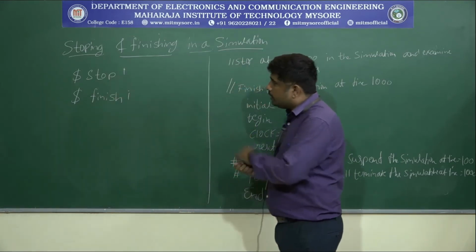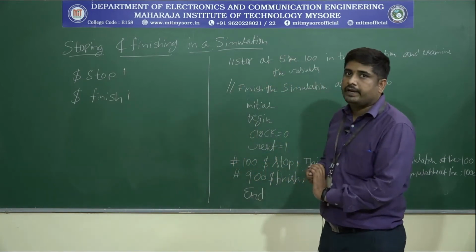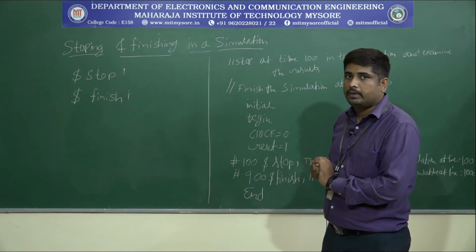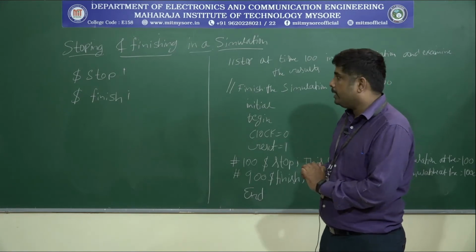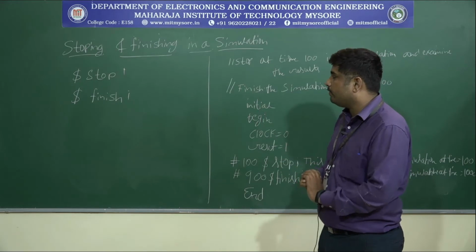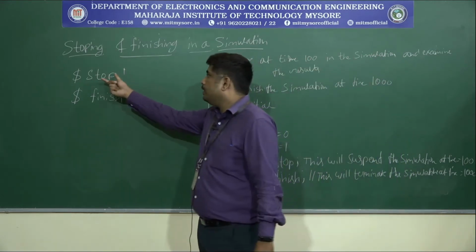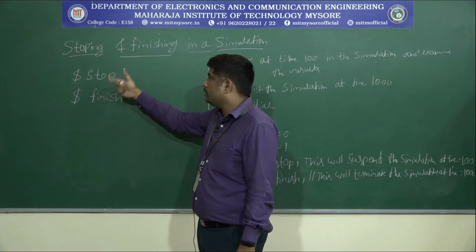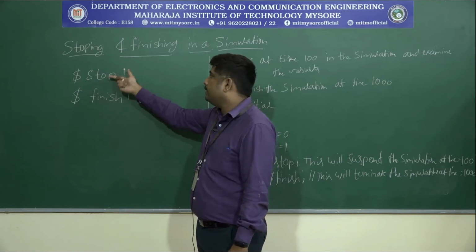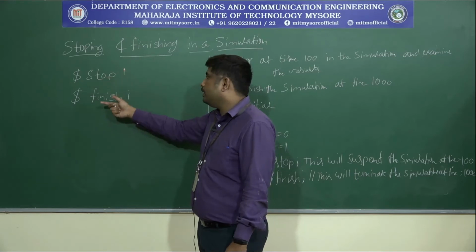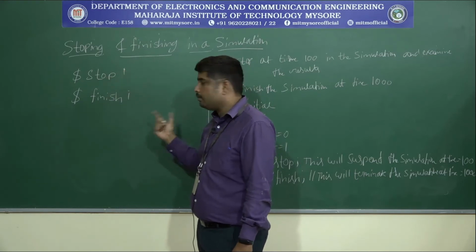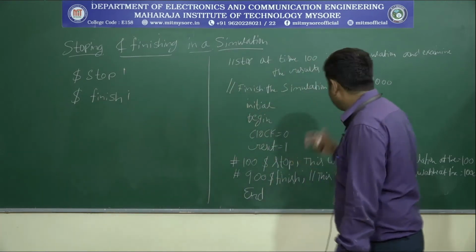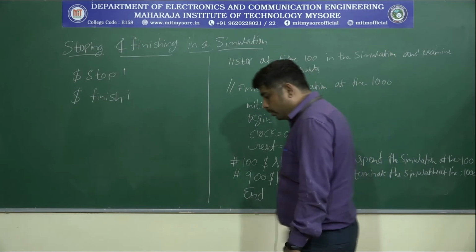Next, $finish. $finish indicates we have to completely terminate the program, that is, the program is completed. At that time we use $finish. So $stop stops the program; if you want to debug the program, you debug it and then continue the program. If you want to terminate the program, at that time we use $finish. So let us take examples for $stop and $finish here.